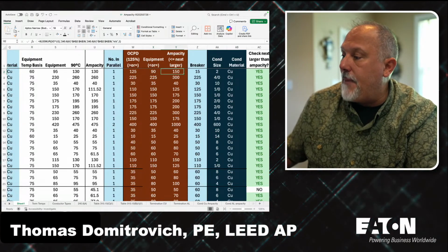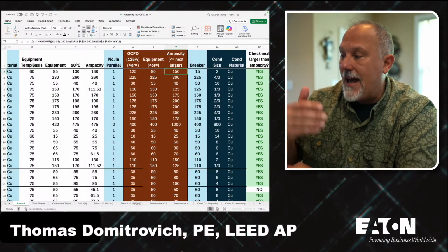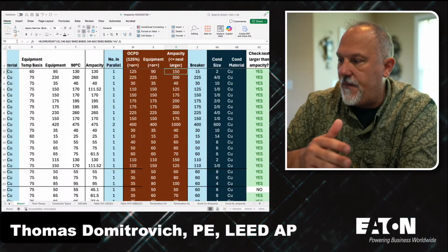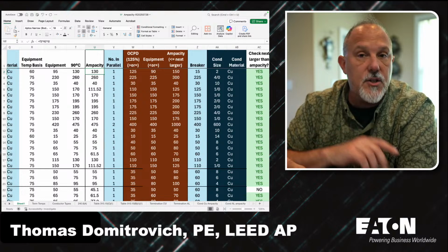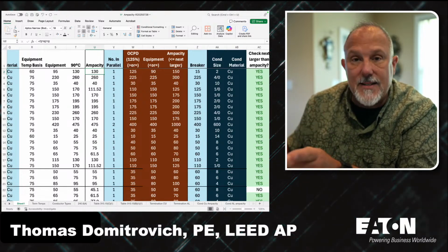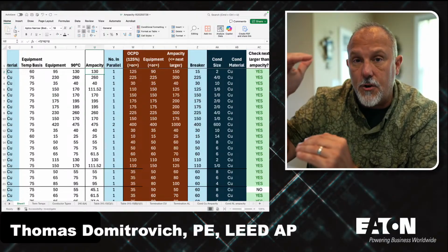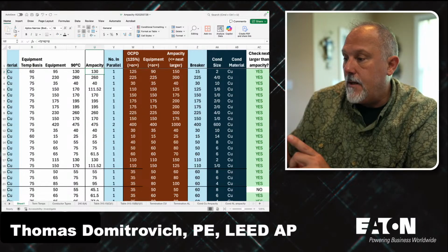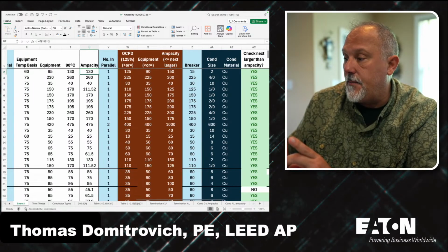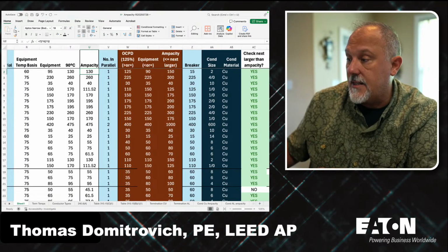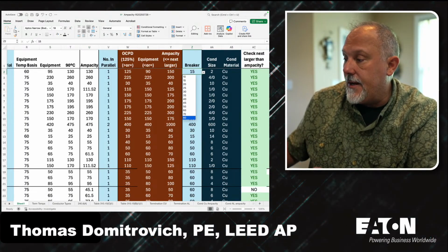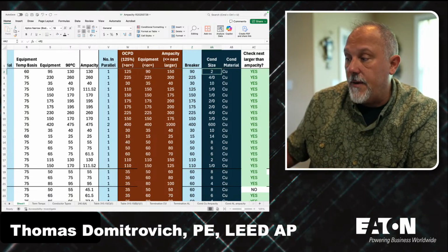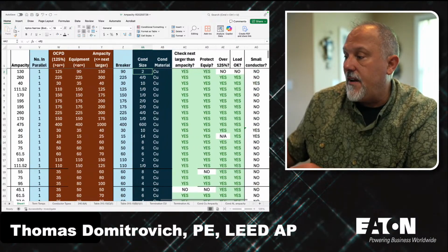And then my ampacity, to protect the conductor at its ampacity, I have to be no greater than 150 amps because I can go, based on 240.4(B), with an ampacity of 130 amps, I can go to the next larger overcurrent device. So my problem with selecting this conductor is probably going to be in this range. So I'm going to pick, since it's a 90, I'm going to pick a 90 amp circuit breaker or fuse, and the conductor size is already, I said it's a number 2, and then this is where I do my values.